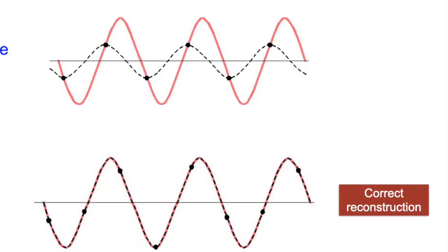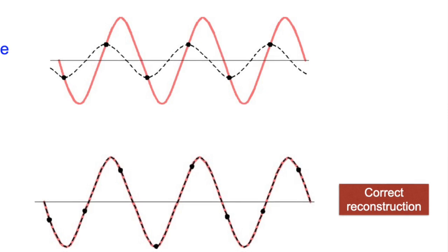And what you see below now in this other reconstruction is a correct reconstruction where we sample a little bit higher. So if you look at the black dots, they're a little more frequent than 2 per 1 cycle of the original signal. And that's how sampling in time works. So again, sampling at the exact Nyquist frequency doesn't work, but if we sample, in this case, at 25% higher than the required minimum, we get a proper reconstruction. And that's part of the magic that we get with sampling. And this is why all these considerations were so fundamental.